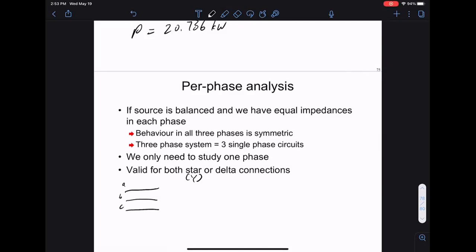Why not? I'm shooting in the dark, but I would assume the inductive loads would be different because B is going to get interfered with by both A and C, no? That's exactly correct. If you look at 3 wires, conductors with space between them look like a capacitor, but there's some asymmetry. B is always in the middle, so it sees 2 equal-distance conductors, but A sees 2 conductors not at the same distance and both to one side. So this is actually not a symmetrical case. But we want symmetry to make everything the same, so we only need to analyze a single phase.